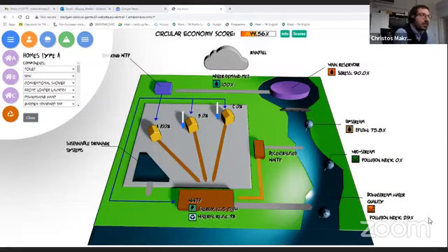You pour that into the sewer. Now the sewer runs all the time. It then conveys the additional solids to wherever it went in the first place, as in the wastewater treatment plant of the city. Actually, as we know, increased organic content for wastewater treatment plants is a good thing. The wastewater treatment plants perform better if the wastewater is less diluted than more diluted, so that's a good thing.